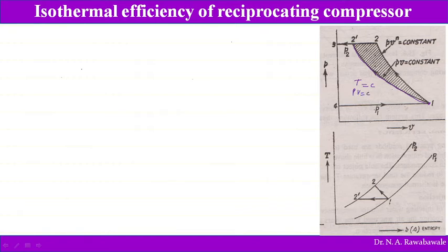The air is compressed in such a way that the temperature is not allowed to increase. That means sufficient time is given for compression, and the minor rise in temperature is not noticed, because the compression process is so slow that the heat generated is immediately dissipated, and compression takes place at constant temperature. That is known as isothermal compression process.